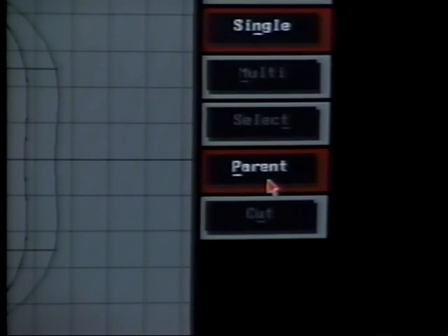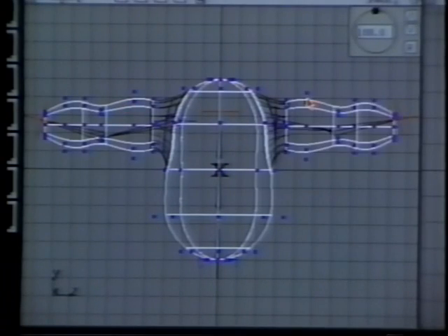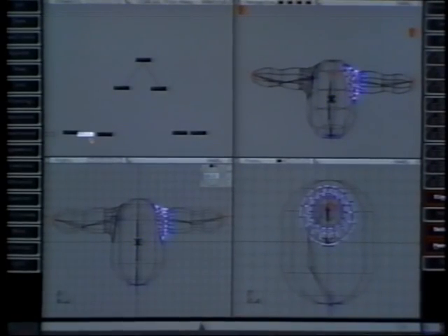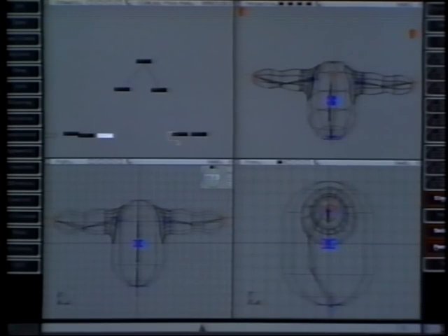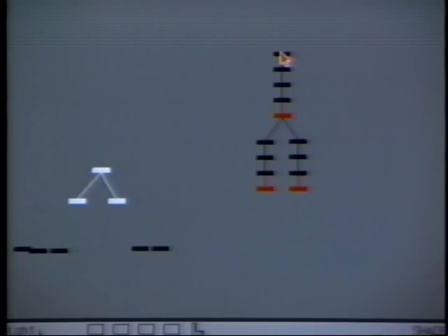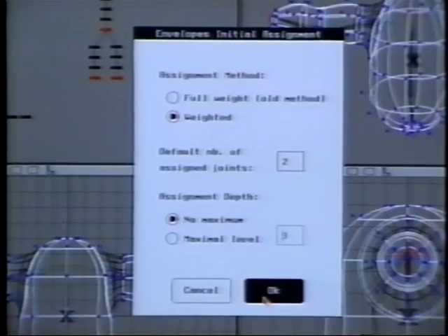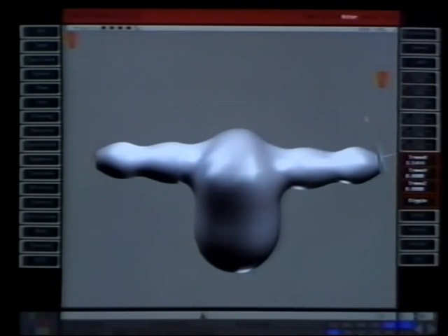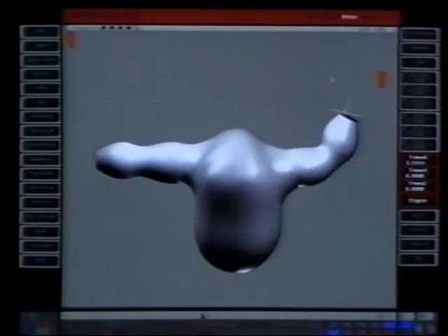The trick with skeletons is just to group together the rest of the character, the base surfaces, but leave the blends and blending custom effect icons ungrouped. The blending custom effect itself will be the only link between the blend surfaces and the base surfaces that we assign to the global envelope. This will update pretty well until we get to too extreme an angle for the deformation, in which case the blend edges can become visible.